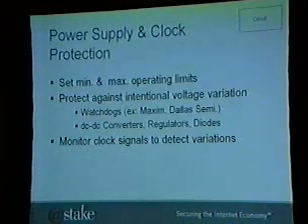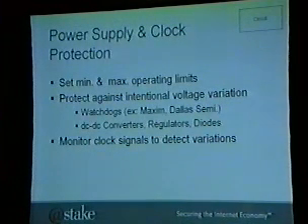And then by slowing it down, we could single step, make it easier to do external measurements with logic analyzers and all those tools. But definitely for time-based things, speeding up the system is going to lead to some interesting things. And one other thing you can do is in many more complex systems, there's actually different clocks in the system. If you could slow one down and leave another one running at the proper time, you can throw things out of sequence, especially like bus transactions.